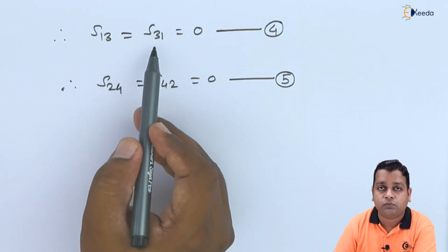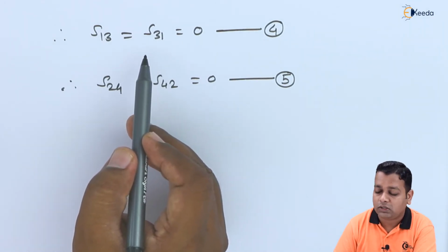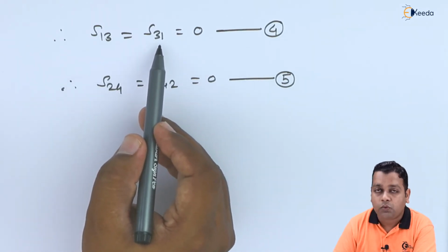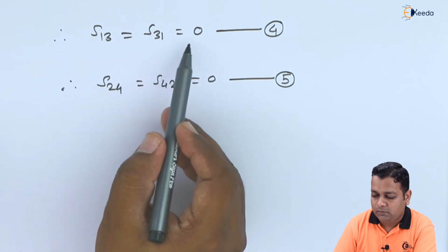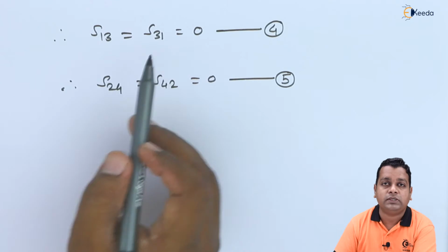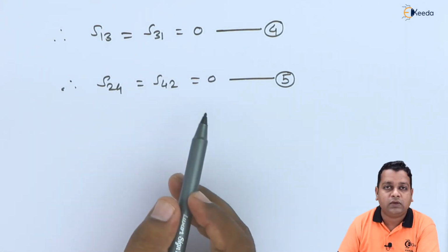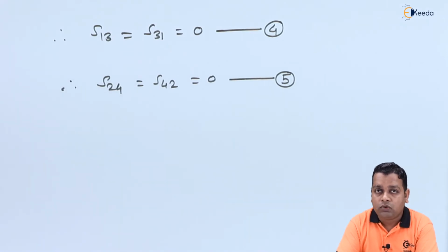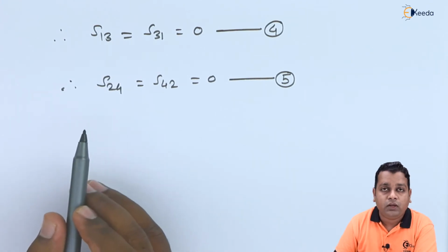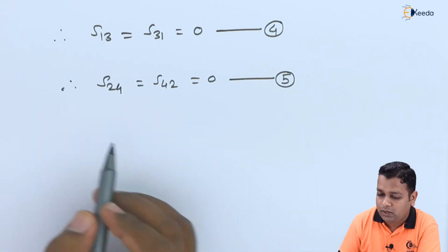There is no chance to provide an output at port number 3, but if it is possible to give the input to port number 3, we cannot have the output at port number 1. The basic mechanism we have seen: it will be cancelling out of the signals due to the phase shift of 180 degrees. Similar is the case if we reverse the directions from port 2, 4 to 1, 3 here. Now we can further make use of these equations 2, 3, 4 and 5.